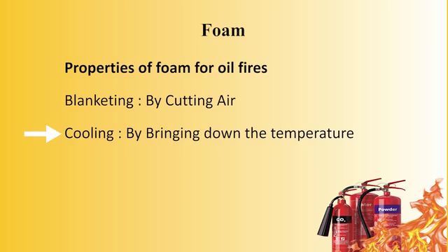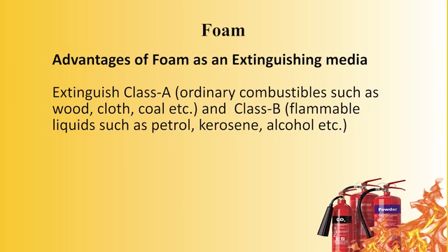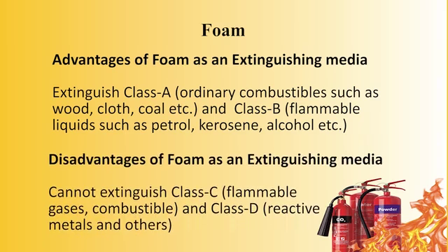Types of foam compound: chemical foam, mechanical foam. Now aqueous film forming foam is the only solution. Aqueous film forming foam. Advantages of foam as an extinguishing media: it extinguishes Class A ordinary combustibles such as wood, cloth, coal, etc., and Class B flammable liquids such as petrol, kerosene, alcohol, etc.